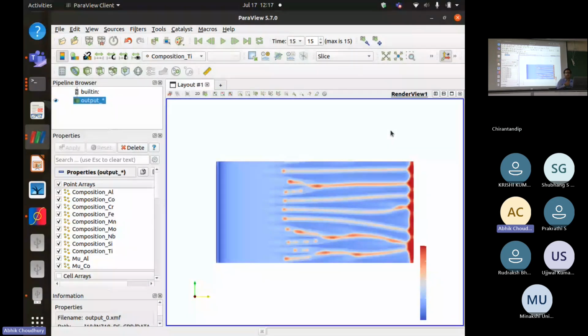We can do a stress applied coarsening simulation of, let's say, CMSX4. This is there in some of our presentations, so that also can be done. So you can simulate rafting, for example, in a real superalloy under heat treating conditions. So you put a stress and the system is at temperature.